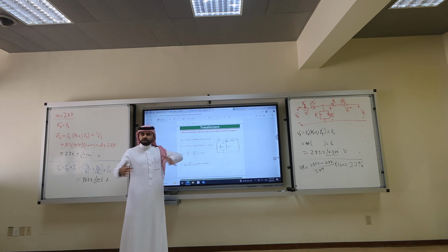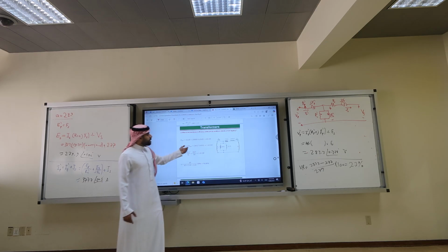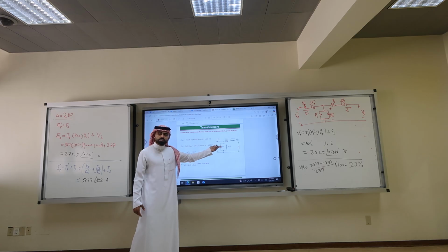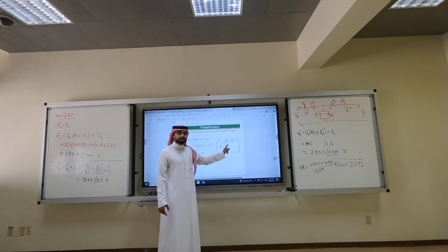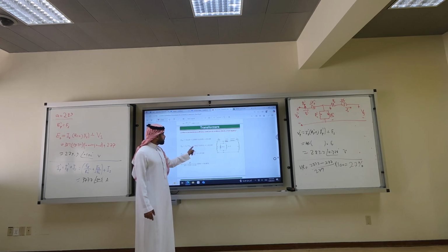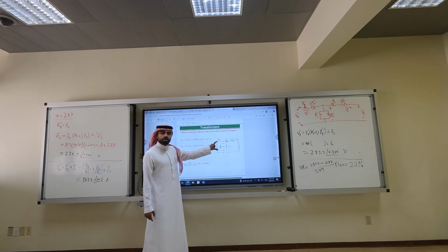Okay, everything is interconnected. What are the copper losses? Here he used circuit 2, referred to secondary. So he combined RP prime with RS into 0.011 times IS squared. What is the core loss? He used VP prime.